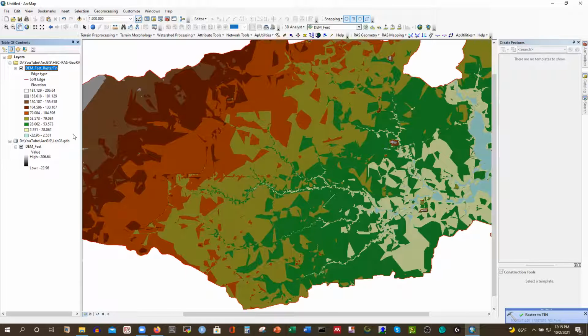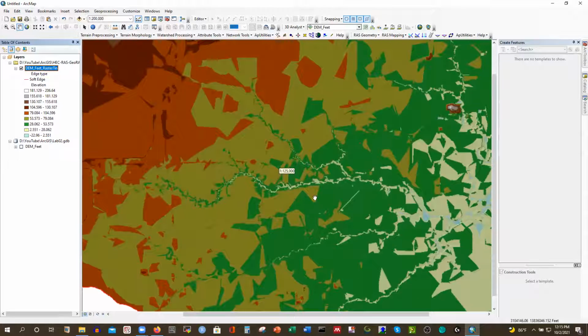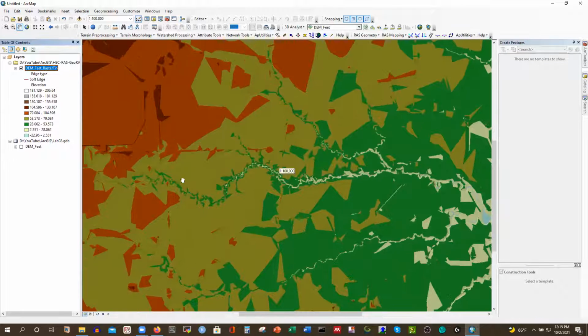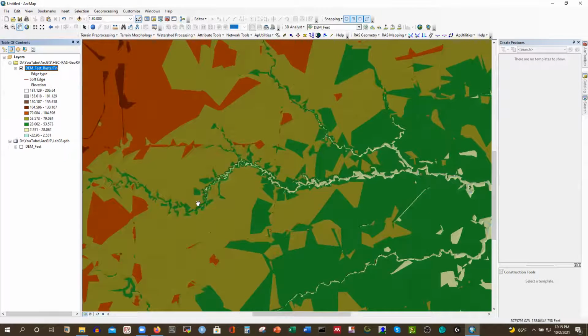It's pretty simple, right? Okay, so I don't need the DEM, so I'm going to work only on that TIN. So I have many streams. Out of these, I'm going to select this simple straight one. At the very first moment, I'm going to quickly show you how to create that HEC-RAS model if you have any single stream, and then I'll show you how to connect the tributary and distributaries.